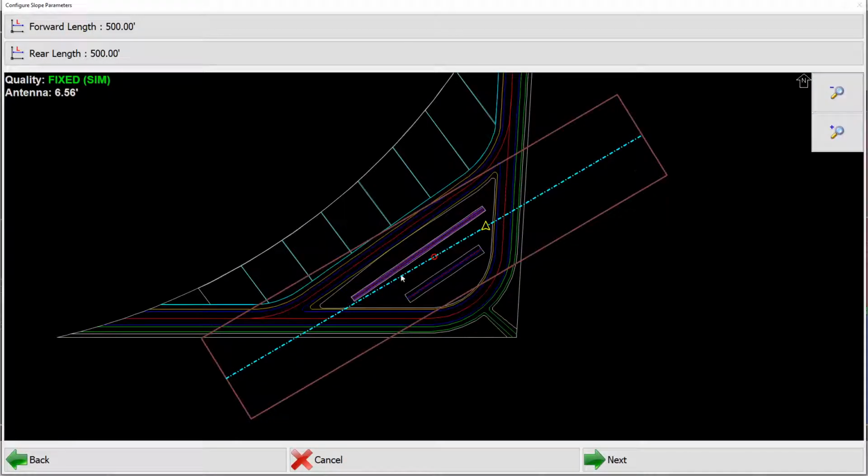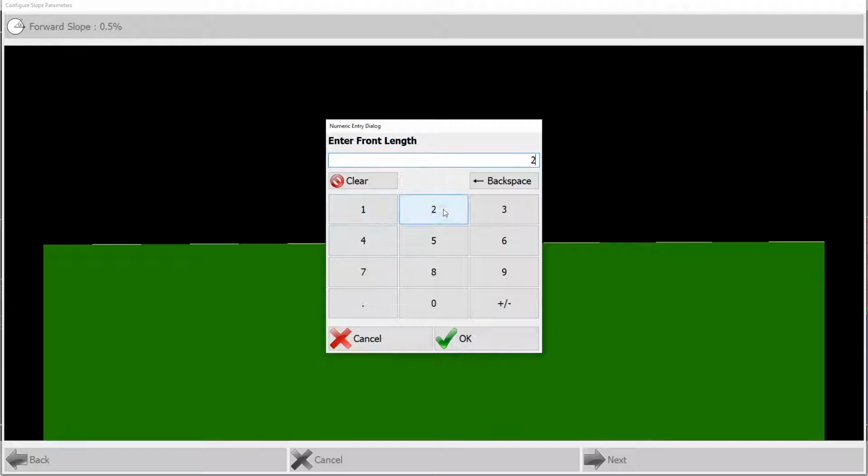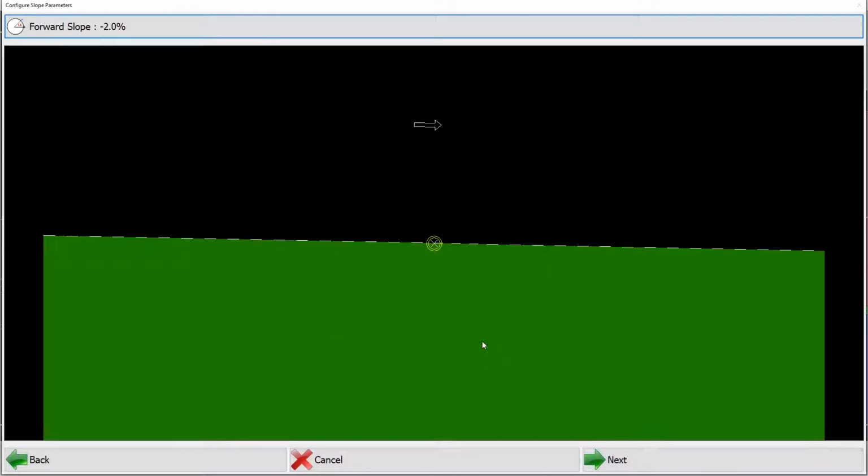It will maintain the main fall slope that you have established. For underground guys, the forward slope will hold the first recorded baseline's elevation, and you can dial in the percent here. For instance, if the first point we shot was the invert of a newly placed manhole, and the second shot was taken at the site of the next manhole you were digging to, you would just enter in the pipe's percent fall and the data collector would take care of the rest. If you shot the 2 baseline points on 2 existing features and you want to grade in between them, then leave this forward slope as is.